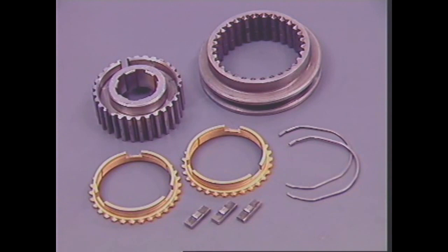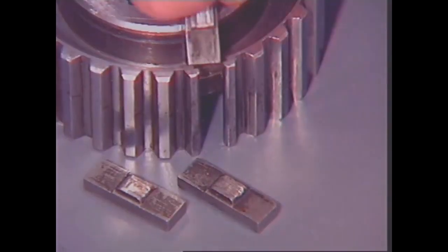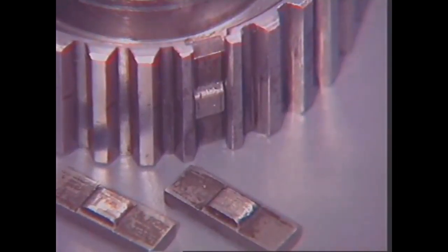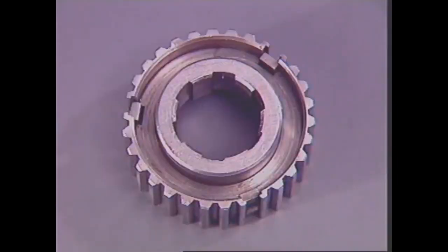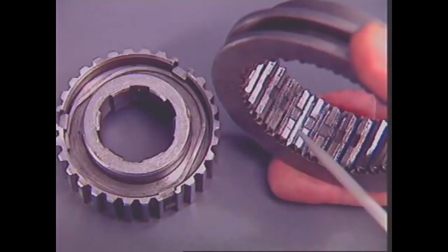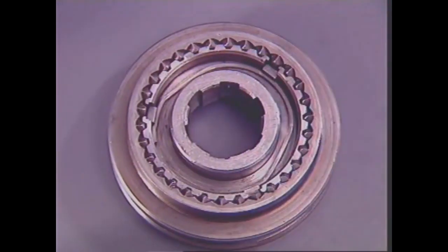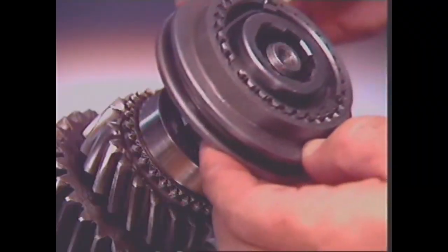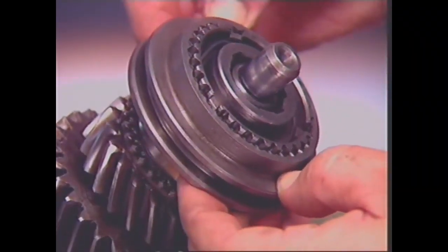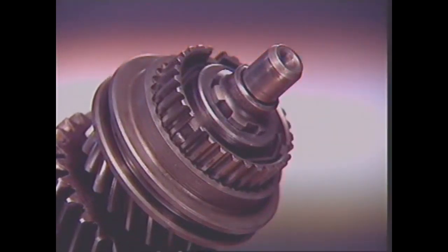A Borg-Warner ring type of synchromesh unit is commonly used to synchronize the speeds of 2 gears before engagement. 3 metal inserts with a ridge fit into slots in the hub. A radial spring at each end holds them out, so that the ridges locate in a groove inside the sleeve and hold it centrally on the hub. When the synchronizer is assembled, the hub is splined to the main shaft, and the engagement sleeve is splined to the hub.